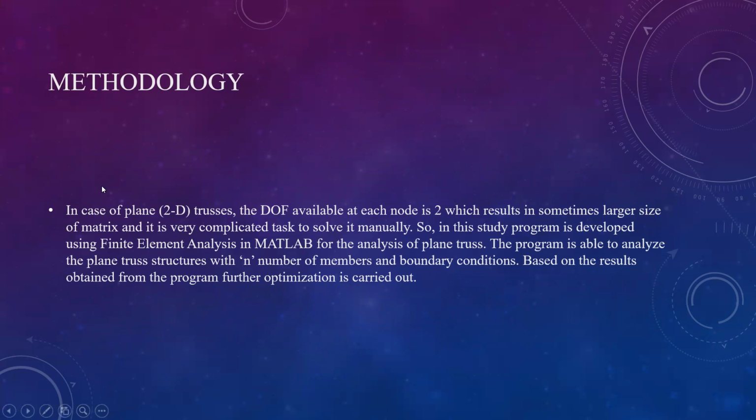And methodology, how do we do it? What is the method included in this finite element method and Matlab? In case of plane 2D trusses, the DOF available at each node is 2, which sometimes results in a larger size of matrix, and it is a very complicated task to solve it manually.